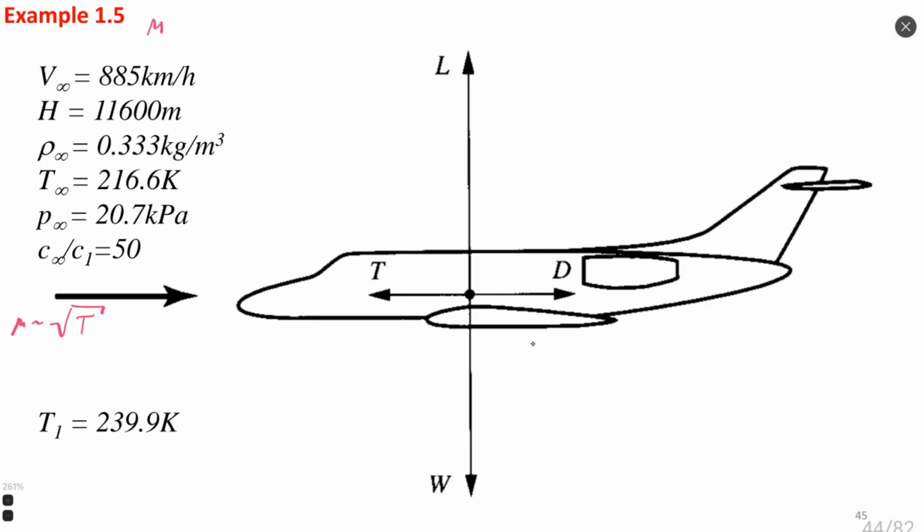Mach number is simply velocity divided by speed of sound, and Reynolds number is velocity, size, density divided by viscosity. I hope it's correct.